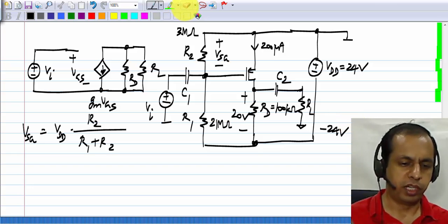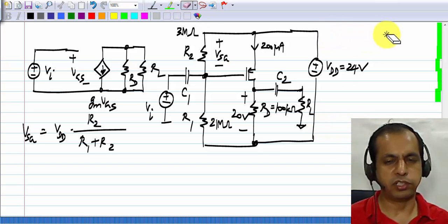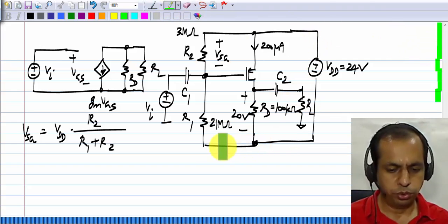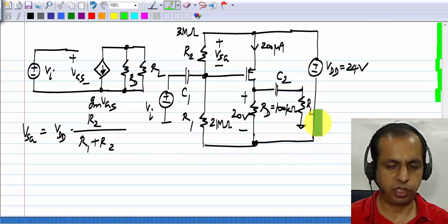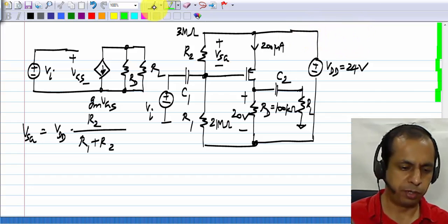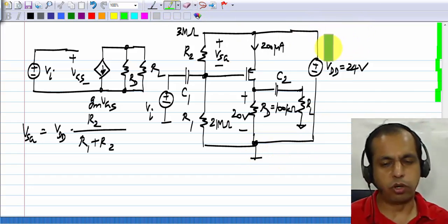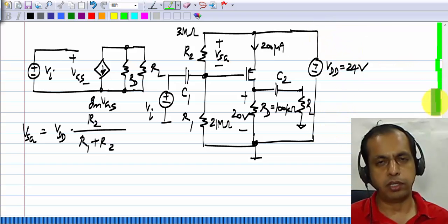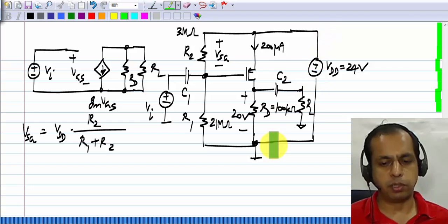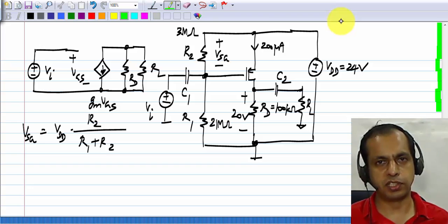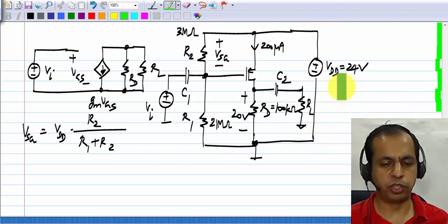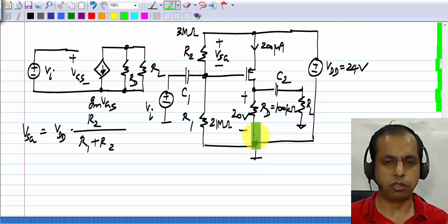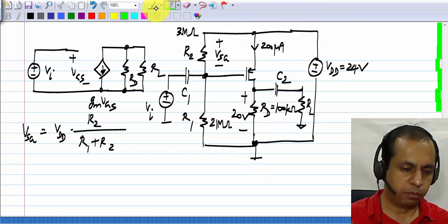Okay. But in case of integrated circuits and these MOS circuits in general, it is common to use the negative side of this voltage supply as ground, so that you think of the circuit as being operated with a positive supply voltage. So this side is ground, and this is quite common whenever you have a single supply. It's not a rule, but it is quite common. Okay. So when you have a single supply, you think of this bottom rail as ground and the upper rail as the supply voltage. There are exceptions to this. Sometimes you do have circuits which run off a negative voltage, but most of the time this is what we do.